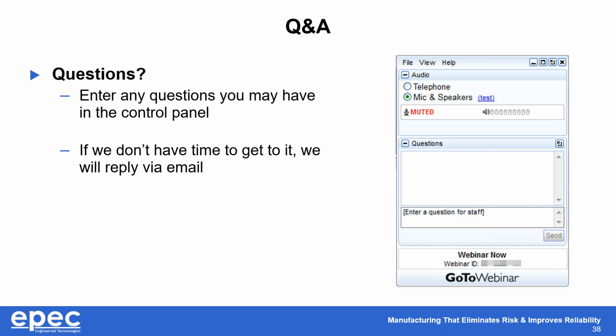Thank you, Ryan. So a few questions that came in. I don't know if I'll get through all of them, but I did mention impedance quite a bit. You're correct. To explain a little bit more about impedance and performance, as I said earlier, impedance is impacted by copper weight, trace length, trace width, and the dielectric where the impedance layer is.